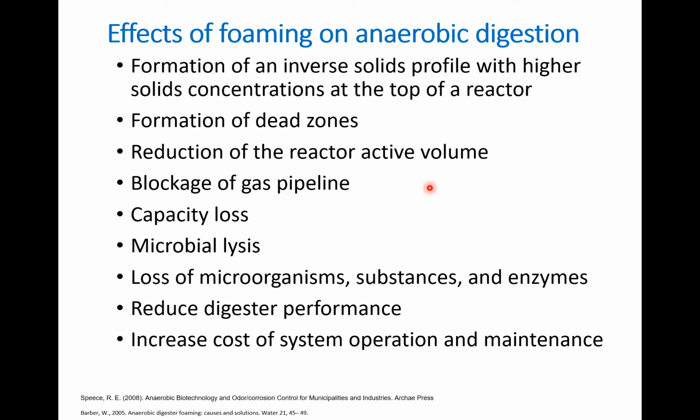Of course, these bubbles can also block the gas pipelines, causing a lot of problems and needing a lot of maintenance. And of course, there is a capacity loss because of the dead zones. If you have these bubbles and some microorganisms around them, they may also cause microbial lysis, meaning less active biomass, and losses of microorganisms, substances and enzymes, because all of these solids accumulate there. They can stay there and maybe also cause scum. Not only foaming, but also scum, a very tough layer on the top that cannot be dispersed easily.